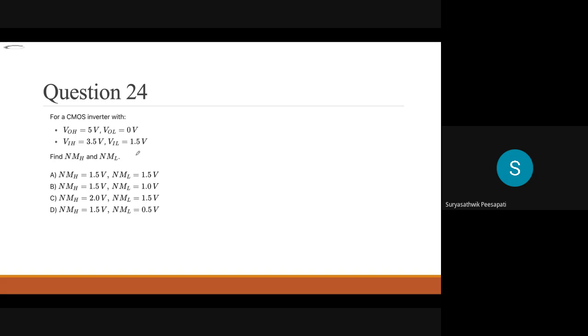NMH is VOH minus VIH. Then NML is equal to VIL minus VOL. Tell me the final answers. Option A. So option A is the right answer.